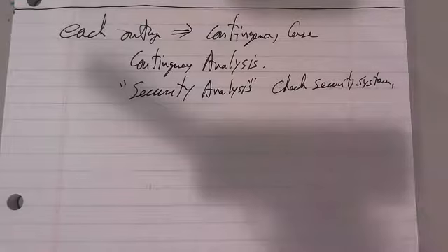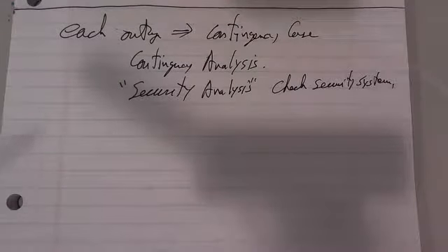Now, it turns out that if you're doing this for a planning system, if you're planning to build a system, you do the same thing. Only you say, okay, I'm going to adjust the loads for 10 years out. I'm going to put the new generators in, and I'm going to put the new transmission lines that I think I need, and then I run the contingency analysis. And if it's a miserable failure, then I haven't done the right thing. I maybe need to put a different set of transmission lines. I need more transmission lines or more generators and so forth.